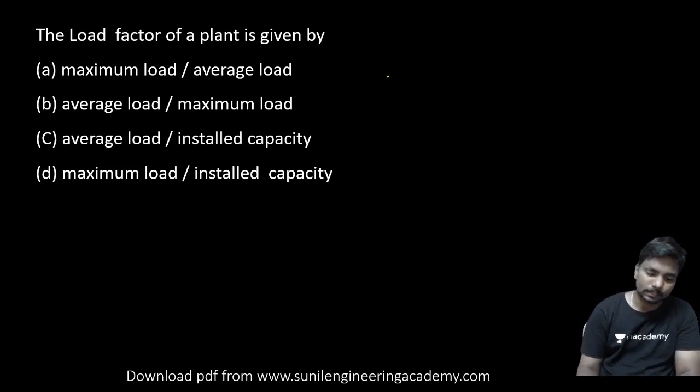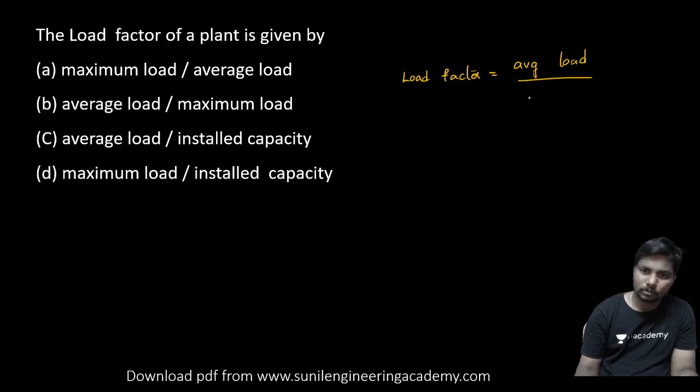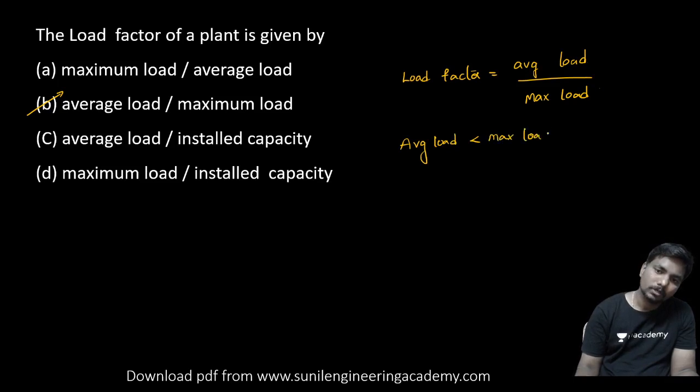Coming to the load factor. Load factor is equal to average load by maximum load. We know very well average load is always less than the maximum load. So that means this load factor value is always less than 1.